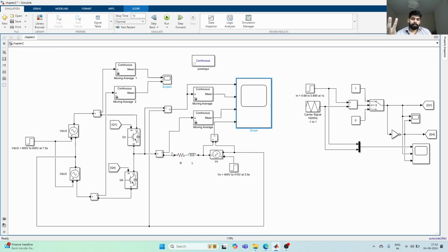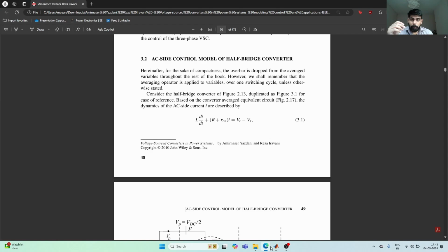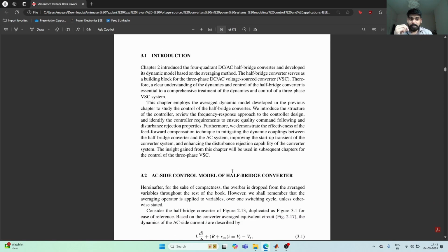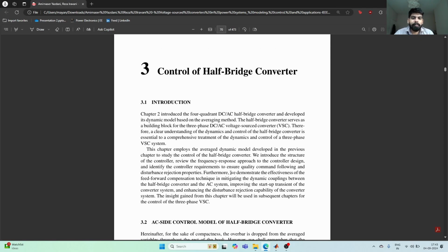At the same time, that control functionality would have the feedback from the plant, or from the system. So basically, this current that we are measuring here, we can take as the measured value, and we take the reference value and try to get the error between this reference and I to zero. And how we usually do that is through PID control or PI control. So today we will be focusing on the control through the PI.